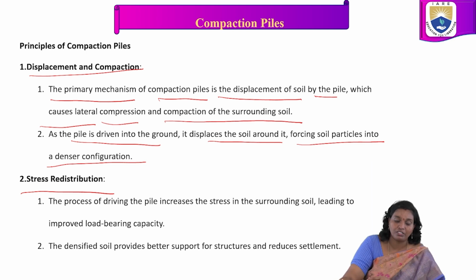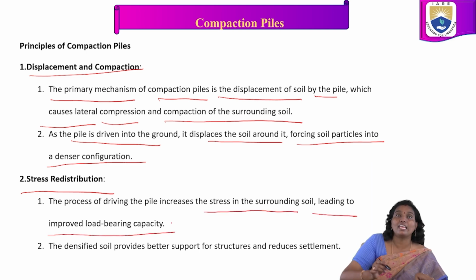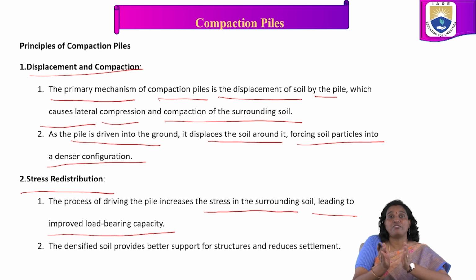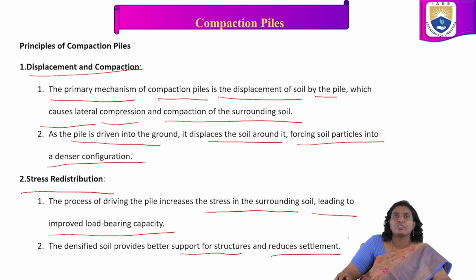The process of driving the pile increases the stress in the surrounding soil, leading to improved load bearing capacity. It means it is going to increase the load bearing capacity. Once we induce this pile, the soil is going to densify. The densified soil provides better support for structures and reduces settlements.